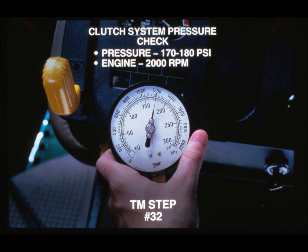Step number 32 checks clutch system pressure. On 50 series tractors, clutch system pressure should be between 170 and 180 psi at 2,000 RPM. If system pressure is within specifications, proceed to the next step, number 36.